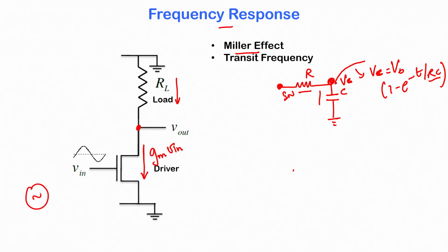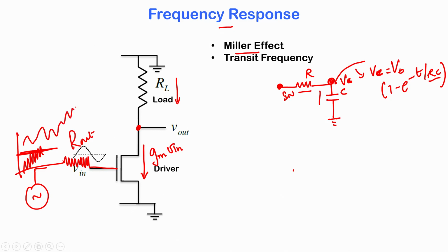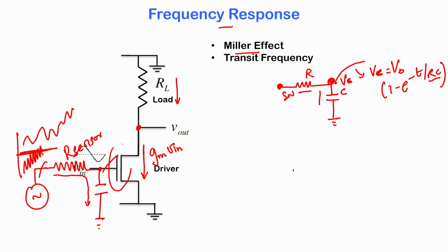We will say that there is a sensor, and the sensor is throwing out these high frequency signals, but sitting at a large DC voltage to keep all this in saturation, and the sensor has got some output impedance and it is sending these signals here. Now when these signals were very low frequency, we really did not care about it, because we knew that the MOSFET could easily respond to these low frequencies. But now we need to be very careful, and in particular we need to identify what is the input RC. So that is the sensor's resistance, and I am now going to be very interested in knowing what the capacitance is at this node, because each time this signal goes up, this RC node has to charge, and it is only then that the gate voltage sees that voltage rise, and it is only then that the current here will change.